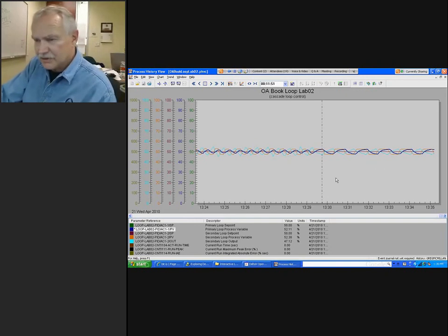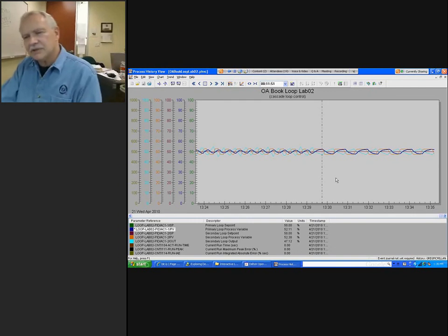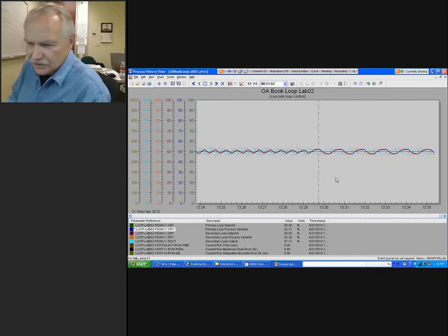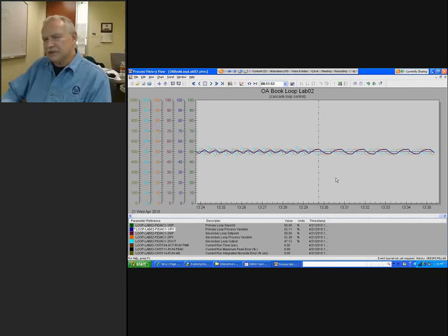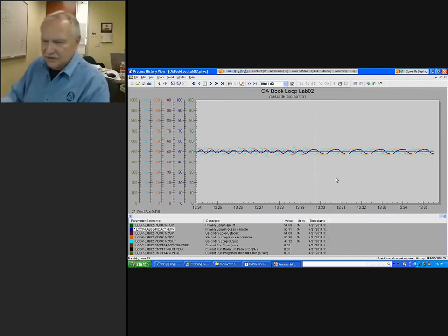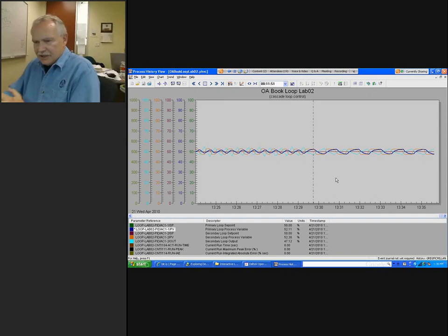1.2% to over 2%. And so by slowing down the tuning of the secondary loop, which you might think is the right thing to do to try and kill the oscillation, actually is the wrong thing to do here on the primary process variable. But also in general, we're trying to filter out oscillations by taking advantage of process volumes downstream, particularly those well-mixed volumes and tanks.